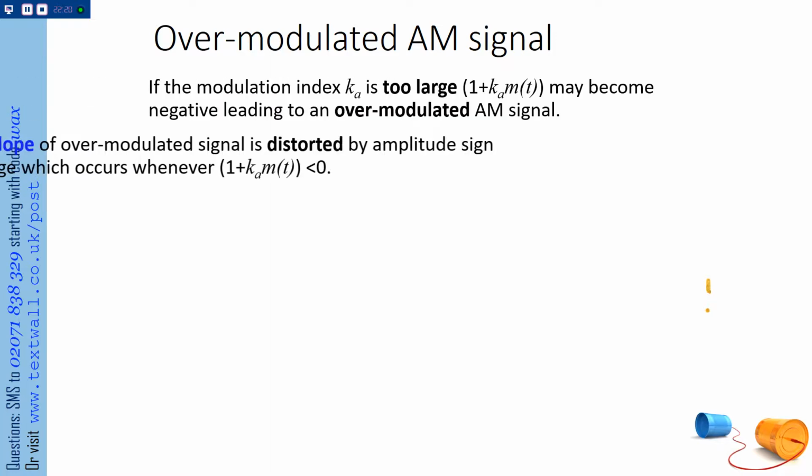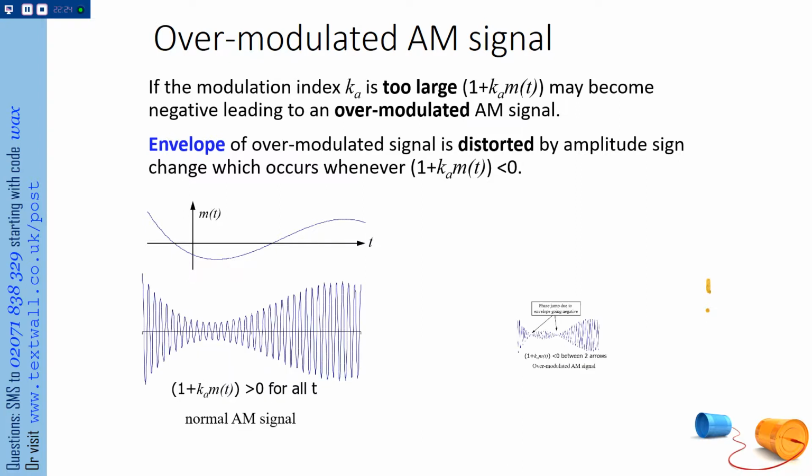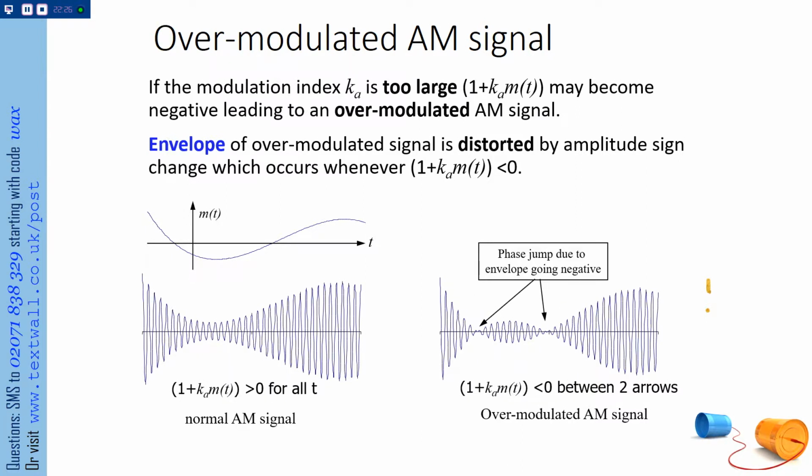So there's something called overmodulation. That's where the modulation index is bigger than 1. It's greater than 100%. That's where the minimum amplitude, so you've got A max and A min. Your minimum amplitude is 0. So you have these 0 crossings. So if you look at the envelope, there, it's still okay, isn't it? It still looks like my message.